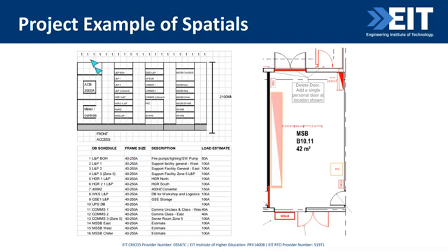And from there, we did a rough calc for a switchboard. The next step was to design the room. So you can see that switchboard was located against this wall, and then we double checked that we had enough room for double plant room doors, for other switchboards to have clearances. This is checking we have clearances in front of the switchboard doors when they're open to make sure our room is not too narrow.